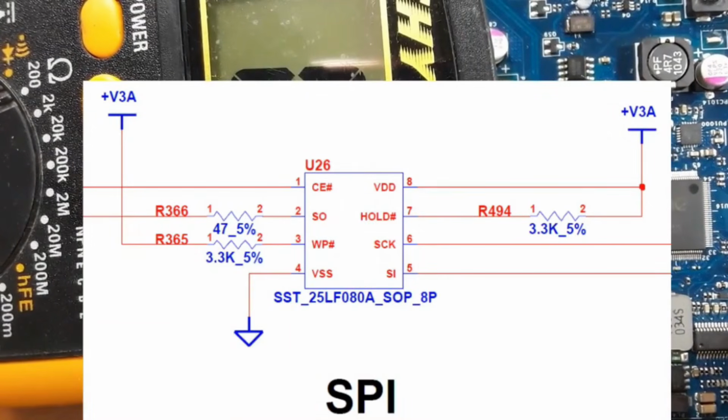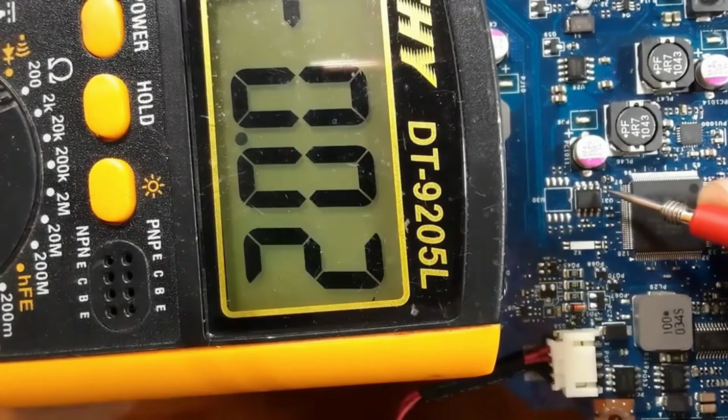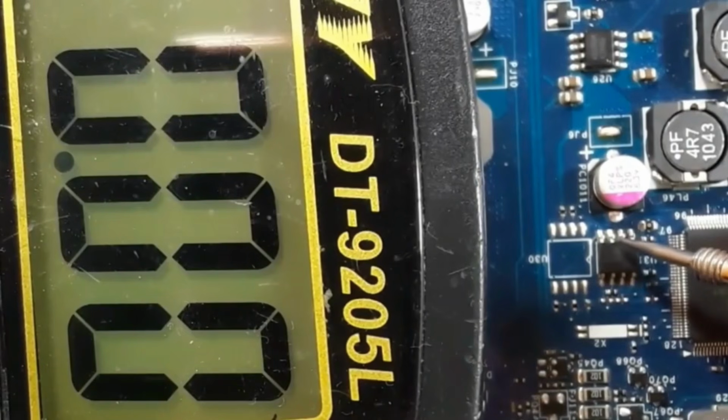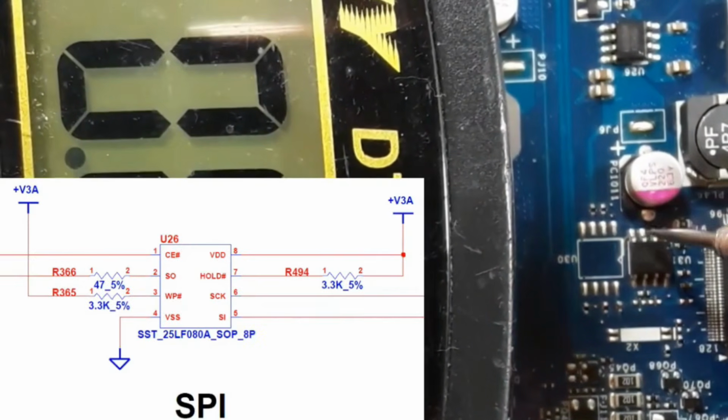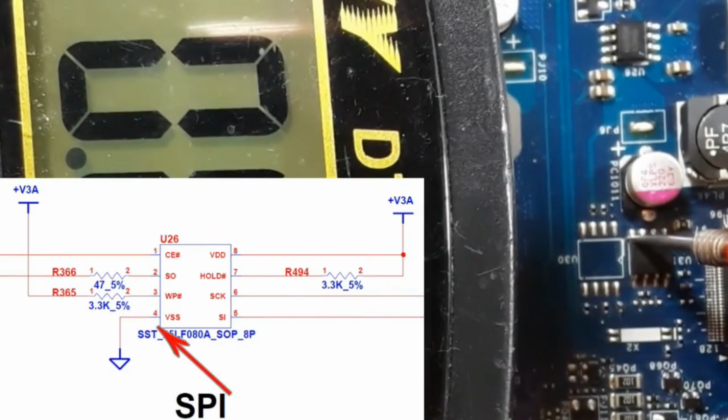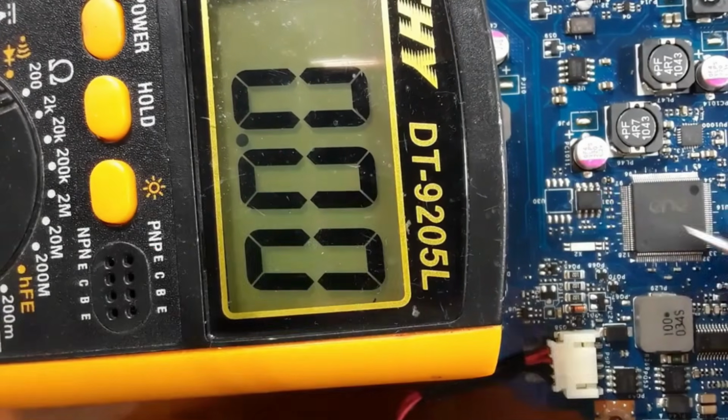As you can see in the schematic, we have 3 volt also on pin number 3. On pin number 3, the write protect, we have 3 volts. So let's check pin number 3. So 1, 2, 3, we should find 3 volt, as you can see. On pin number 4, we will find 0 volt because pin number 4 is connected to the ground.